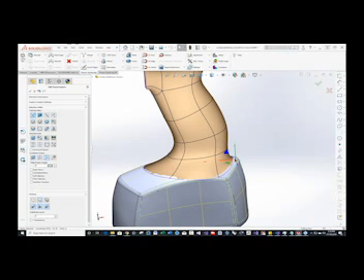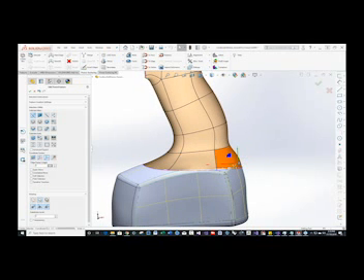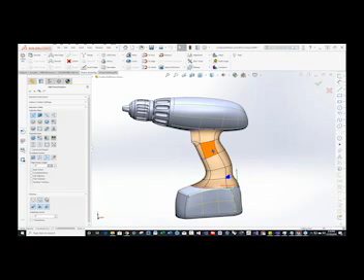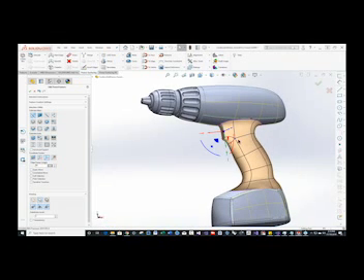So you can see now it's inside on just this surface. And then if I pull it back down here, you can see it flows right over that fillet edge because it's tangent. You can see this one does as well. So as long as they're tangent, you don't need to have a break. If you had a creased edge here, you would in fact need to put one of these breaks on there and deal with it slightly differently. But that's sort of an atypical situation. And you can see up here we've put some partial creasing in, so that's like a 50% crease to prepare for where the trigger will go.